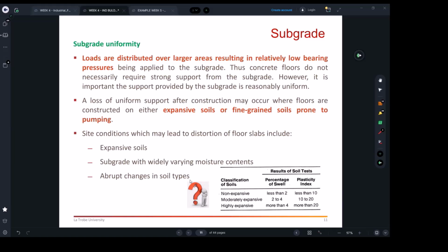So when they take away the vegetation, the soil moisture content will be very dynamic. It will not be stable, and you need to think about ways to get it stabilized. As I said, you either wait for several months, or you can dehydrate the soil. And sometimes you see in the topography that the soil properties change.